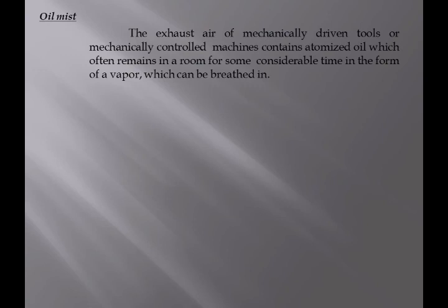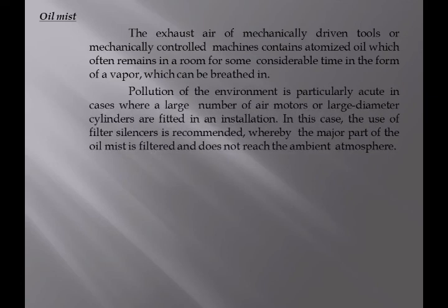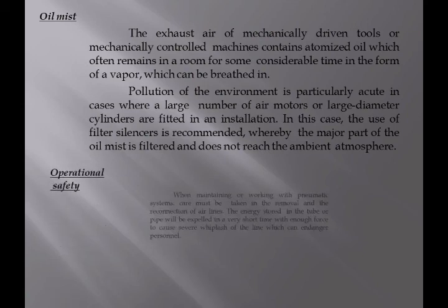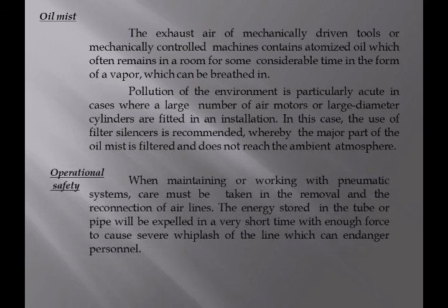Oil mist. The exhaust air of mechanically driven tools or mechanically controlled machines contains atomized oil which often remains in a room for some considerable time in the form of a vapor, which can be breathed in. Pollution of the environment is particularly acute in cases where a large number of air motors or large diameter cylinders are fitted in an installation. In this case, the use of filter silencers is recommended, whereby the major part of the oil mist is filtered and does not reach the ambient atmosphere.